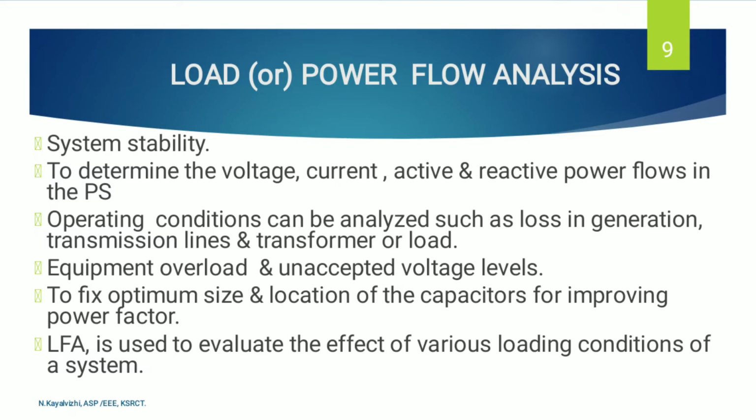Operating conditions can be analyzed, such as losses in generation, transmission lines, transformers or loads, and which equipment is overloaded and where unexpected voltage levels occur. We must also fix the optimum size and location of capacitors for improving the power factor. Load flow analysis is used to evaluate the effect of various loading conditions of a system.